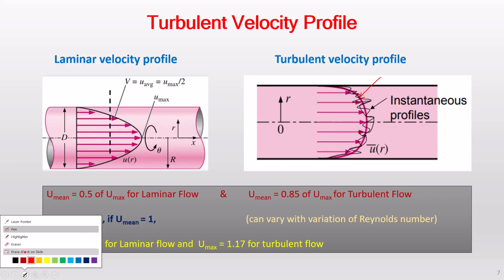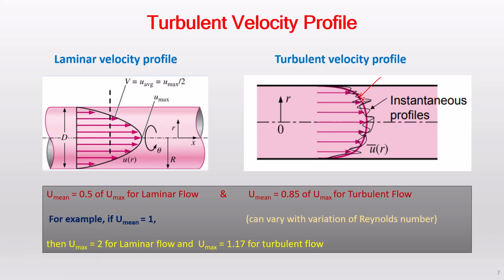Now this means that if I want to predict the turbulent flow, I have to not only solve like we do in the laminar flow, where we solve the equations for the velocity profile like the du by dy, or du by dr actually. So we write it as dy because we are solving in the xy coordinates, but the y coordinate is actually representing the radial coordinate, and the x is in the axial direction. So when you solve the problem as two-dimensional, otherwise three-dimensional, everything is like x, y, z. So here we have to take care of this change as well. So that is called the fluctuating component.